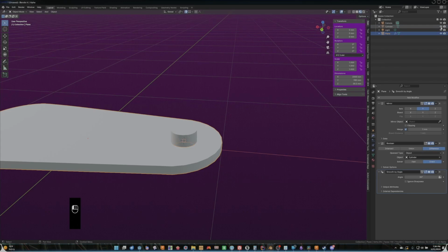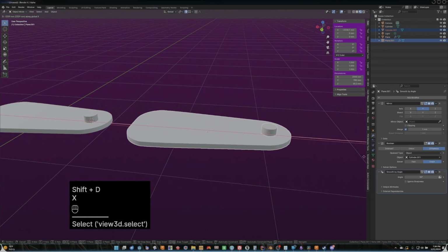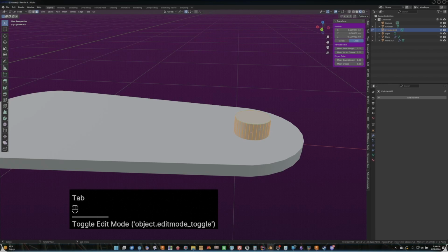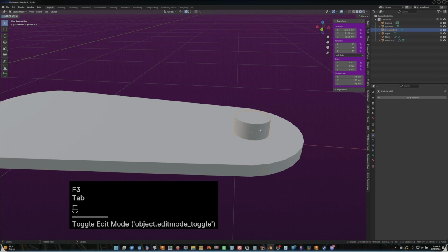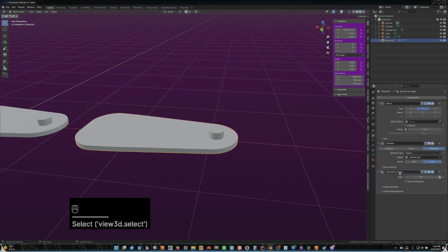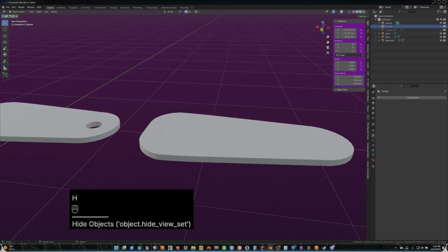And I'm just going to demonstrate that for you. So I'm going to take our dog tag and our tool, and copy them over here. And what I'm going to do is flip the normals. My keys aren't working. There we go. And then F3, and then flip. So now our normals on this object are flipped. And I just want to show you what it does before I show you why. So with our Boolean tool selecting this object, if I get rid of it, you notice that there's no hole like there is with this one.